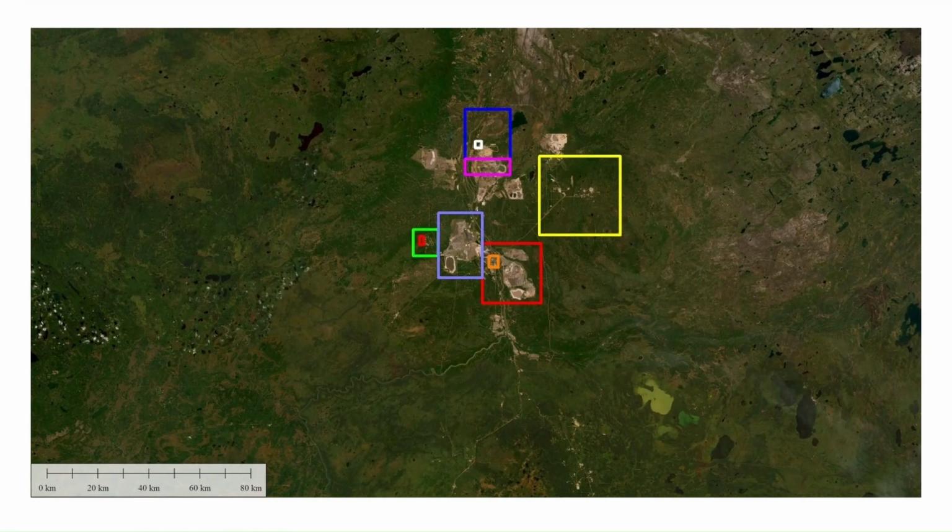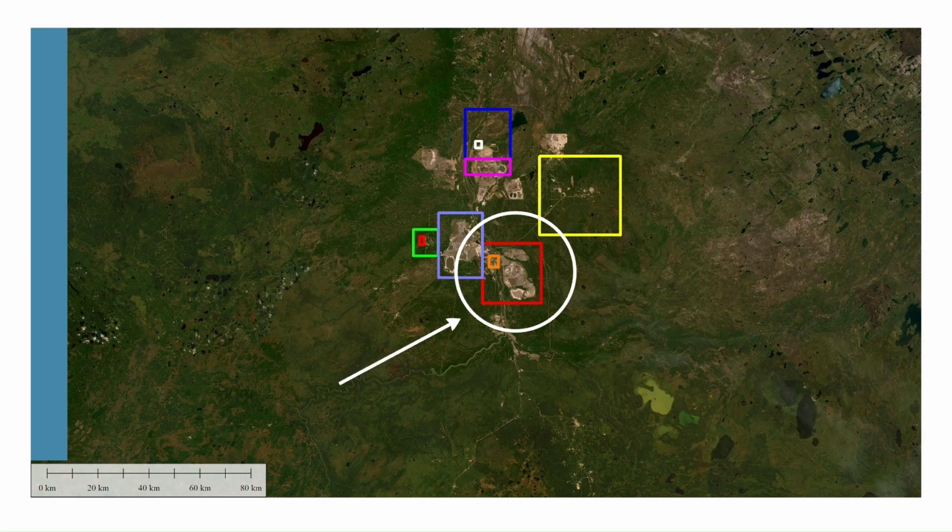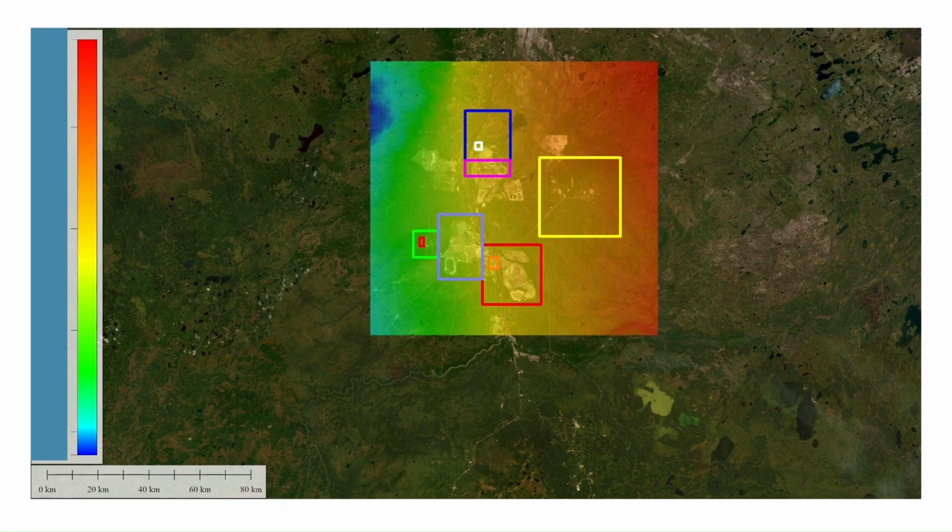So let's take a look at that area again. Let's take a look at these two, that orange, the base plant, and the red square, the base mine. The first two grids we built were for that. Here's the one grid. This grid goes from CGVD 28, Canadian Geodetic Vertical Datum of 1928, which we still use, to that base mine, so the red square.